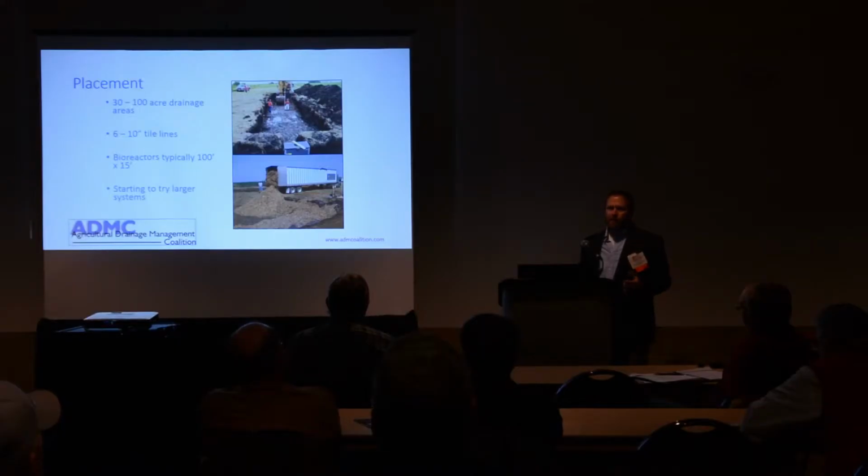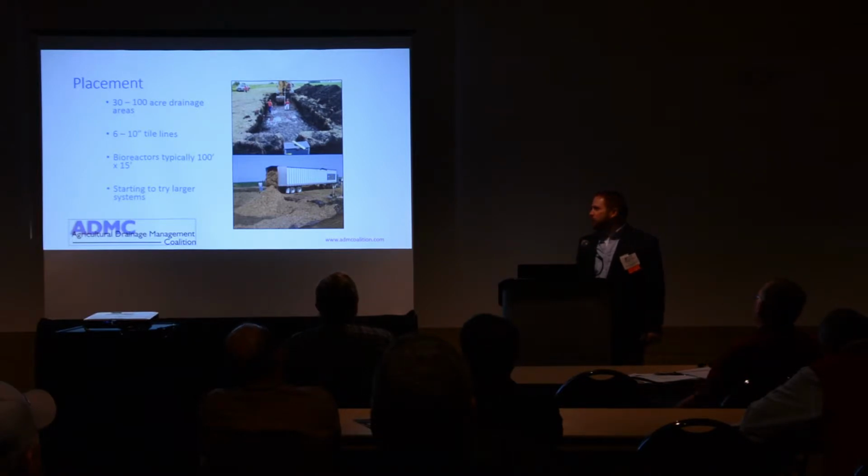The longer the bioreactor is, the more retention time that water is going to be interacting with those wood chips. How wide the bioreactor is tells us how much of that peak flow of the field tile it would treat.